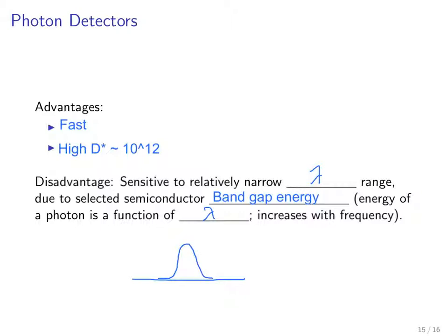So let's say we have a given spectrum to which we are sensitive as a function of lambda for a given photodiode. This would be the sensitivity, or the detectivity, D star, of the photodiode, whereas a thermal detector is going to have a much broader, albeit lower, specific detectivity. As we said, they are pretty much lambda independent.